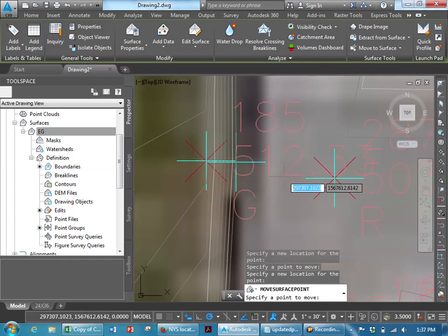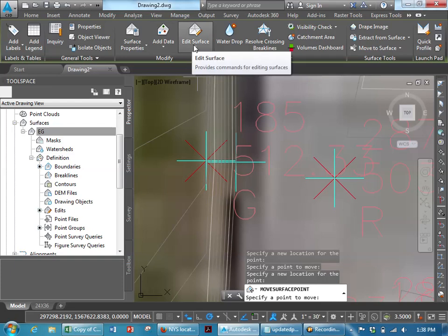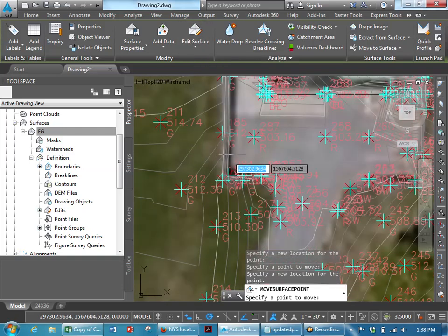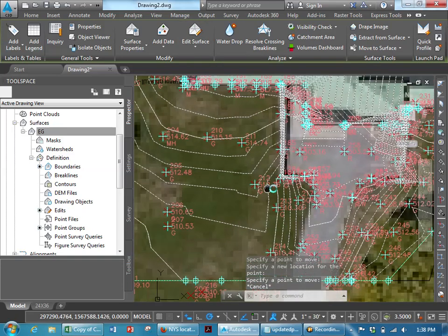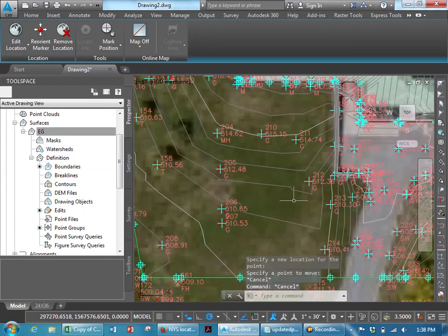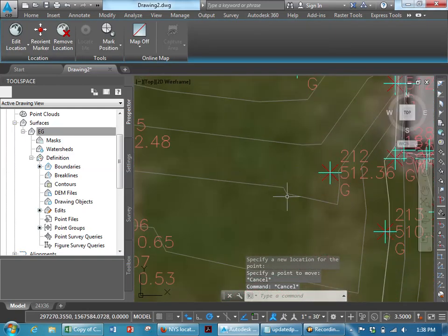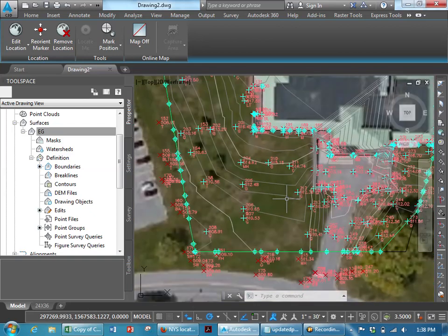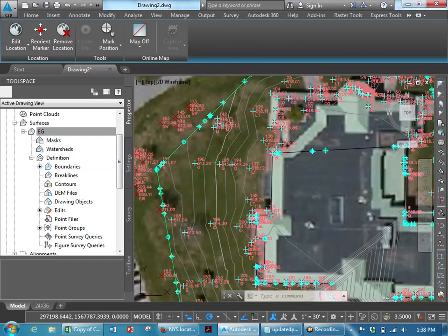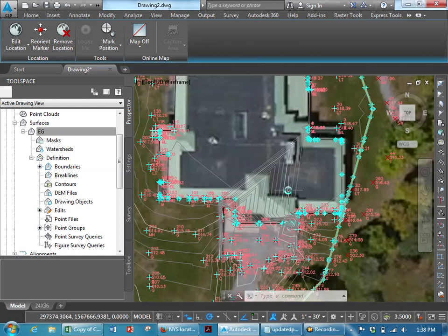Make sense? Or if you put a bad point in, you can go in and delete it. So I wanted to go over that with editing contours in the building, vertical steps. Contours are appropriately smooth. Generally, like this is appropriately smooth. If you get a lot of really weird things going like this, you might want to go in and tweak those a little bit by either adding points or seeing where CAD has their points. But generally, this isn't terrible here. But if you get things that look like that, again, you're going to need to delete them using a boundary, right? So weird things like that.